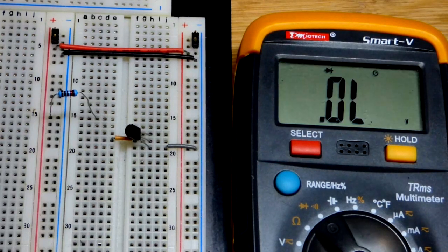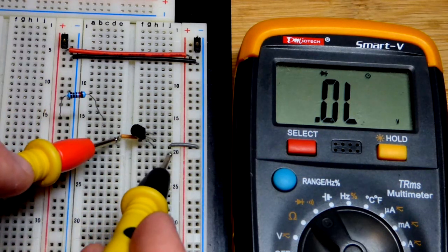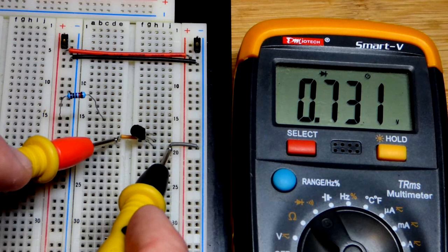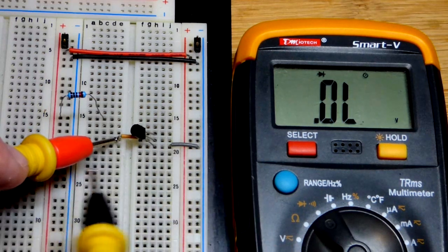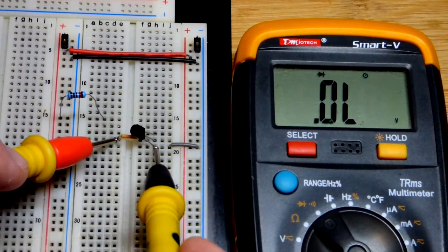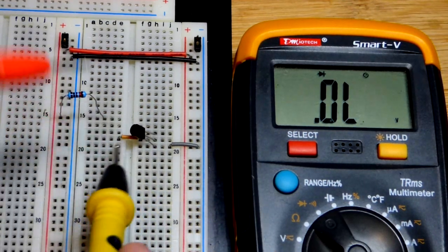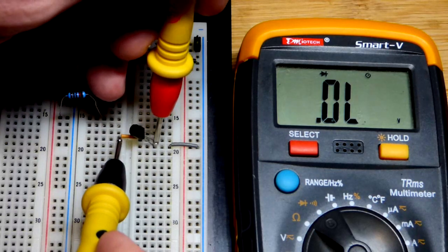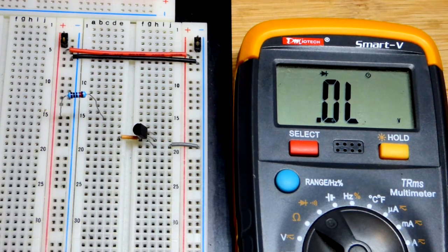Now we have the little diode schematic symbol. I know that the middle jumper is to the base, and then the emitter is down here. As I said before, it's a forward diode, somewhere around 0.6 volts, and at higher currents it'll be 0.7 volts. So it'll be somewhere in that range. And the collector, same thing. So that's how you can find the base. If you get, with the black probe here, a low voltage reading of about 0.7 volts on each side, where the red probe is will be the base. If we put the black probe on the base, we will not get any reading when we go to those two, because they both need more voltage than the meter is applying to test it.